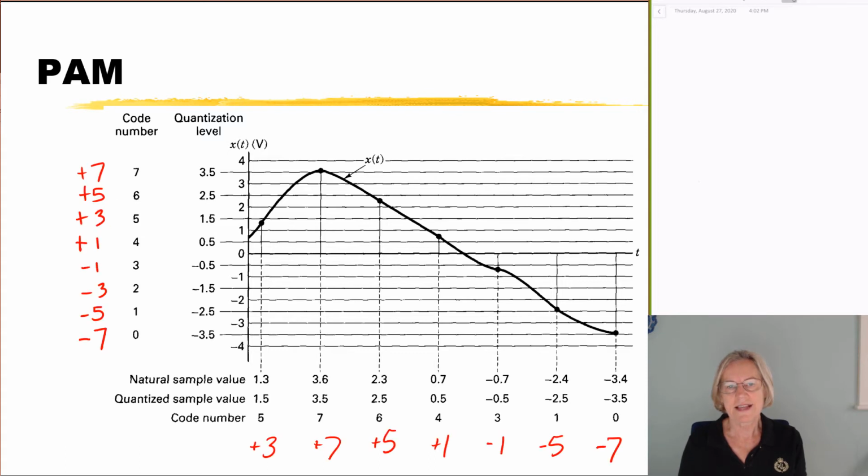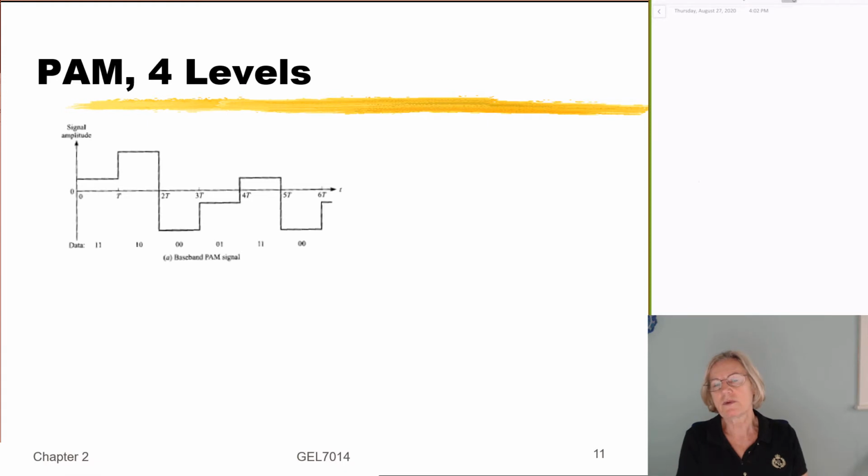So now let me take a specific example, and explain to you what the implication of that is. And I'm going to just simplify it a little. Let's say that there are only 4 discrete levels, and that each of these 4 levels could correspond to some 2-bit sequence. So for instance, here's my +1 level and my +3 level, my -3 level, my -1 level, and there's an equivalence between this +1 level and the bit sequence 1, 1, between the +3 level and the bit sequence 1, 0, etc. So when I quantize my analog signal, I can either send it in this PAM multi-level signal, or I could use a PCM signal where I send this bit sequence. And they're essentially conveying the same information along our digital communication system.